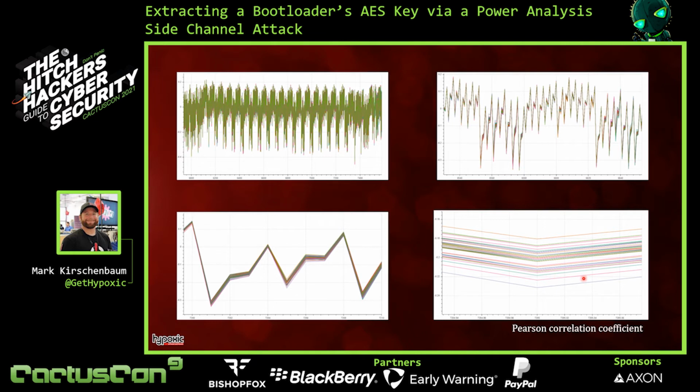Now that's where the two different types of side channel power analysis go, is how to process this change. We're working on the correlation method. So there's really a thing called a Pearson correlation coefficient, which will allow us to basically figure out what the value is by how the data correlates with each other. And luckily for us, the software will do it for us. At the end of the day, all we're going to be doing is throwing this power trace into software. We're going to say what kind of leakage model we have, and it's going to help us come up with the end keys.